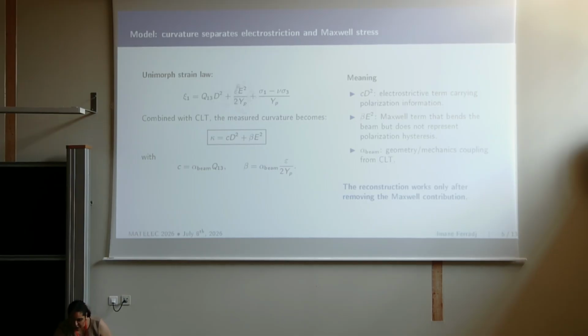And we have the Maxwell effect, which is due to the presence of the two electrodes sandwiching the active material. And so we have an electrostatic force resulting in this term called the Maxwell effect. Usually it is neglected in some materials. In this case, we don't neglect it for this material because we have high dielectricity and a slightly low Young's modulus.